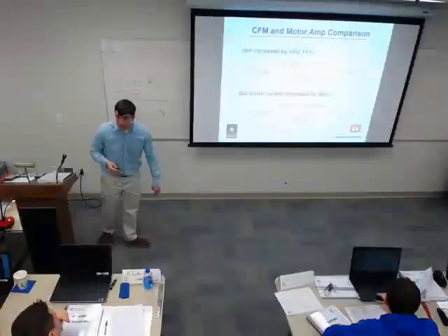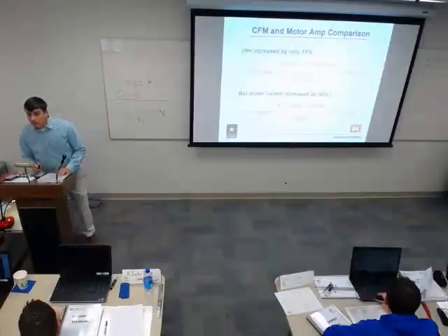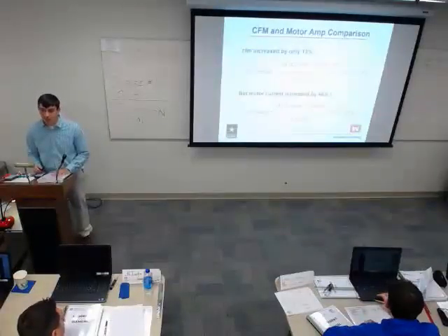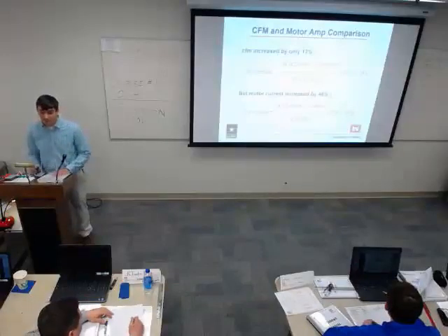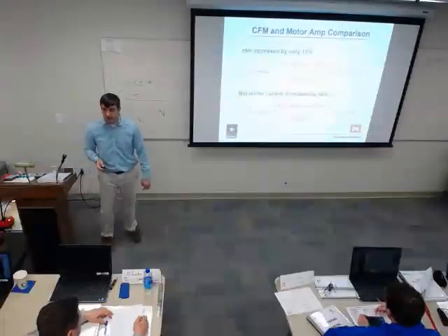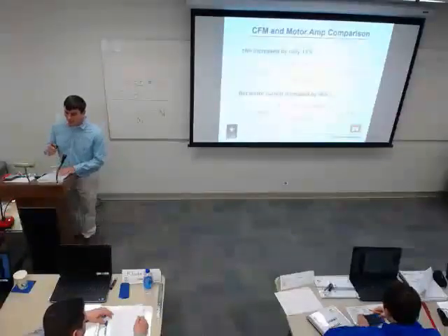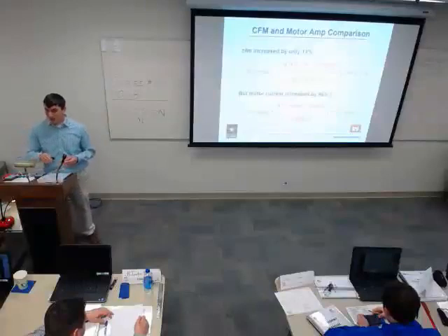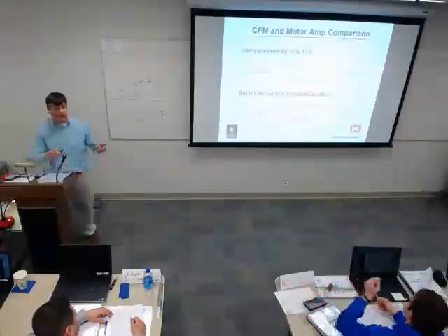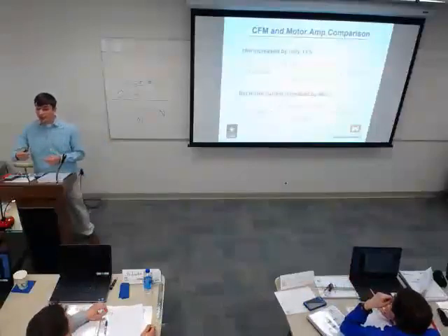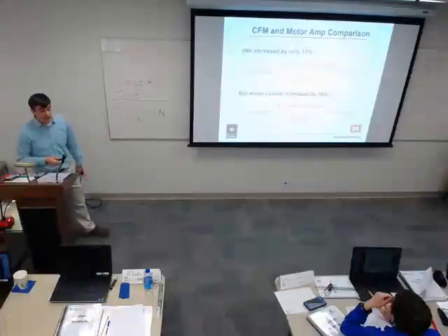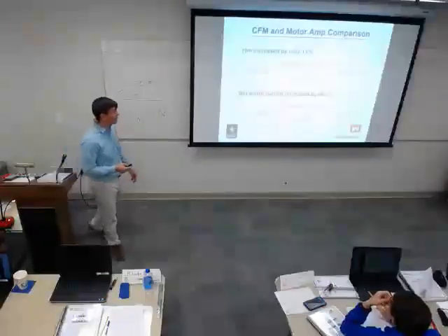If you've got a VFD and you say ramp it up, you'd be in the same situation. Yep. It takes that much power to move that much air. Because I hear people all the time saying, well, let's dial it up. Which you can, as long as you're not exceeding your electrical system rating or your motor rating. Or we also talked about that fan curve earlier. We had the class 1 and class 2 fan ratings on the fan curve. I'm going to show the fan curve again in a minute. Make sure you're not exceeding your fan classification as well.